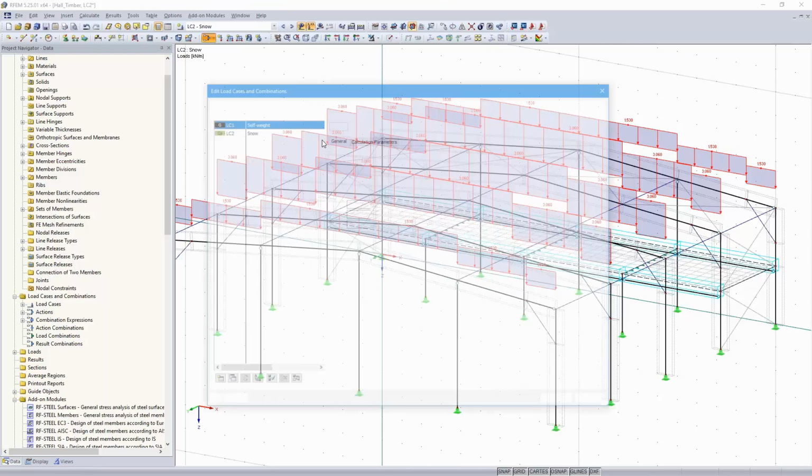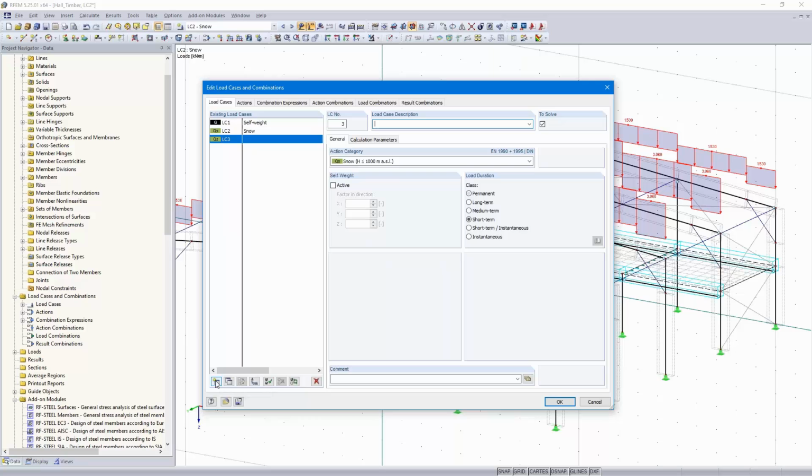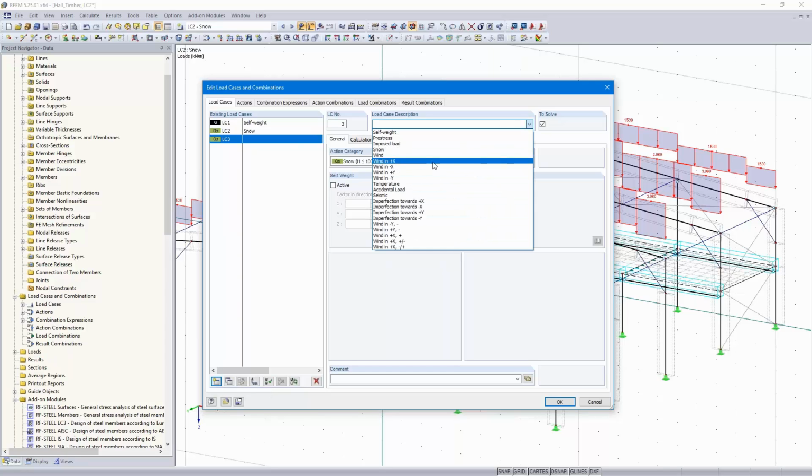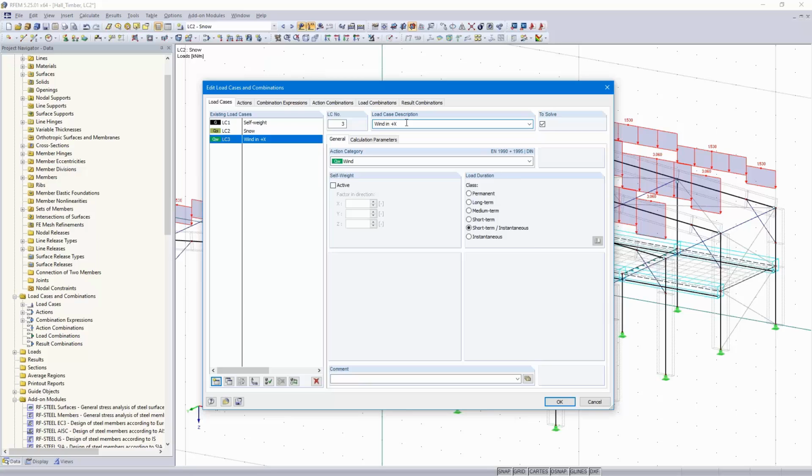Okay. So new wind load case, wind in plus X with pressure. I copy that, then with suction, and pressure, and pressure and suction. Okay, these are the 4 wind load cases for wind direction 0 degree.